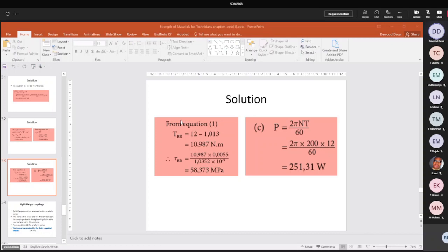You got to have covers like a kettle. How you got the cover? So they put two covers at the ends and they weld it in a circumferential joint with the weld. Okay, sometimes they use both. Most of the time they use weld. So that's how they make a pressure vessel.